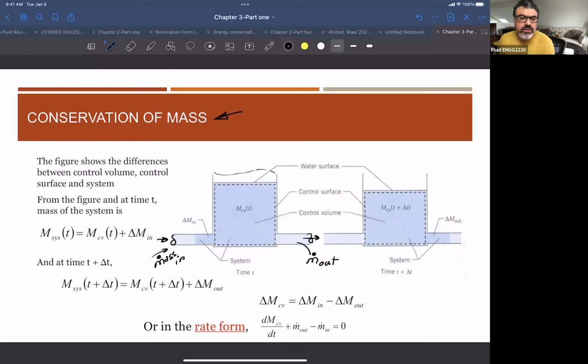But for a flow between two plates where one plate is moving with a certain velocity, what is driving the flow is the plate. That means the maximum velocity is the plate velocity, right? So it has nothing to do with that. But average velocity is looking at the average quantity of the flow rate divided by the area, which will give you an average flow rate. If you are referring to the mass, it's going to be the average velocity, not the maximum velocity.